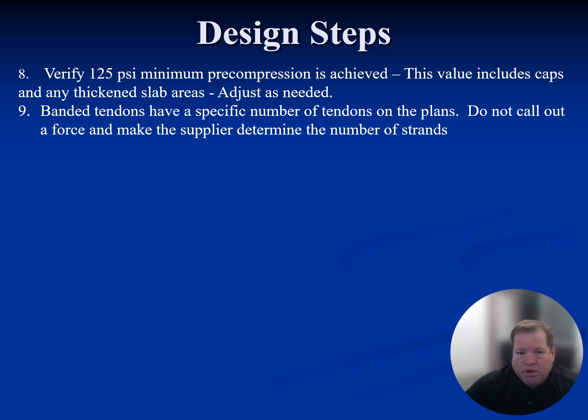As I mentioned before, it's prescriptive. It's thou shall be greater than 125. I would also say that if your design is 125 and it's working, your slab's probably too thin. Again, we're more in the 175-200 range, so I typically don't deal with the 125 value that often. And if you are dealing with it, you might want to look at your slab thickness because you may be a little bigger than you need to be.